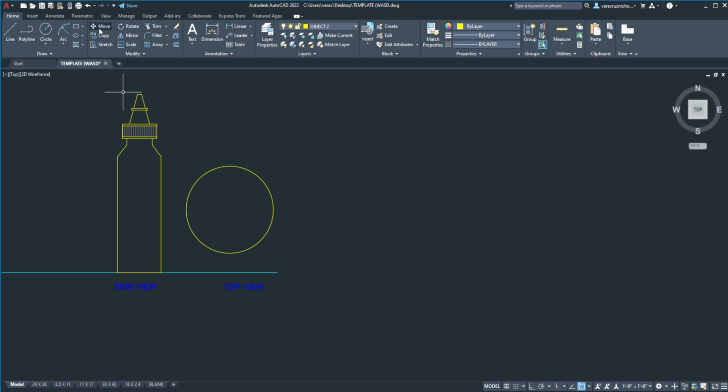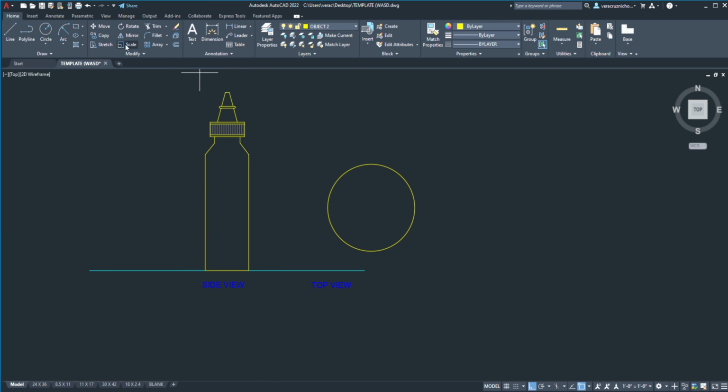We are going to move this one a little bit over to the side. There we go. And while we're at it, why not just extend this, or let's just stretch this a bit more. There we go. And now, actually, it'd be easier just to do this, grab the line, make it your own. Escape, escape, MA to match properties, mother, father. Escape. There we go. Let's organize this one as well. Make it up there in the middle, to be more aesthetically pleasing.